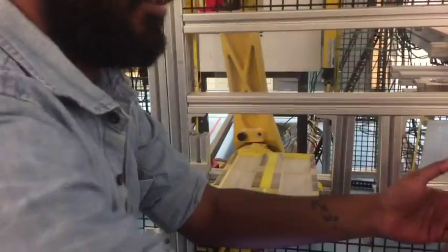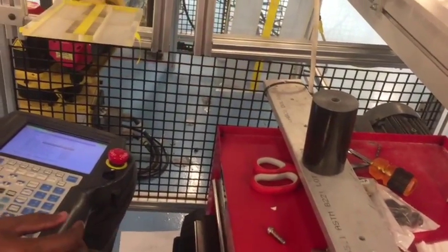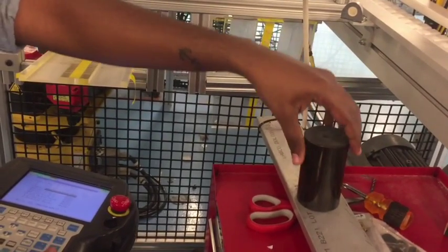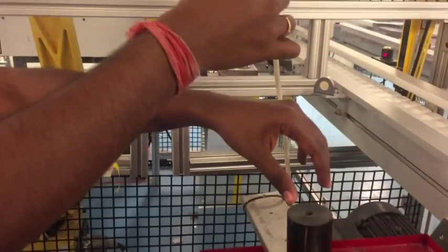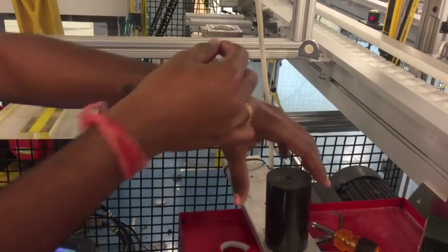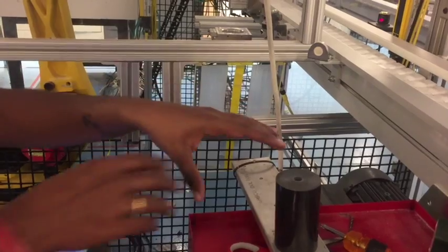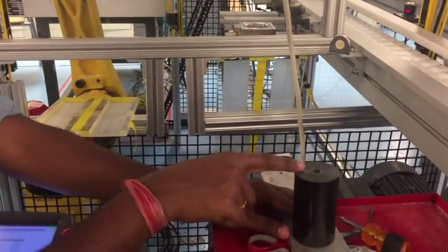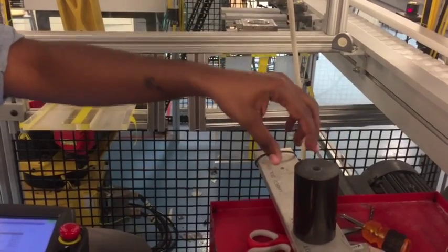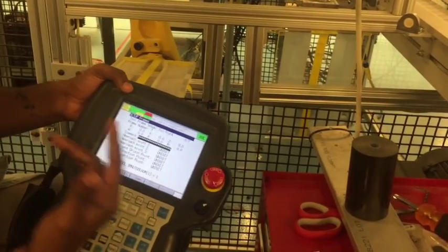If you want this particular frame, say this is your particular frame over there, and the arm has to go in and operate. Since the default tool frame is about a particular height, it's pretty difficult to program the robot to pick this part or do any of the functions in that workspace. So in order to define a frame on this particular point, you need to define all these 6 points: approach 1, approach 2, approach 3, and so on.